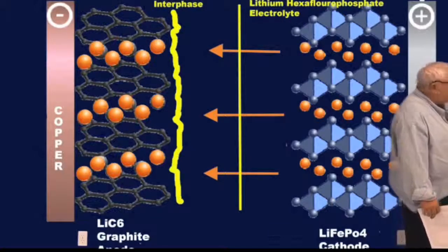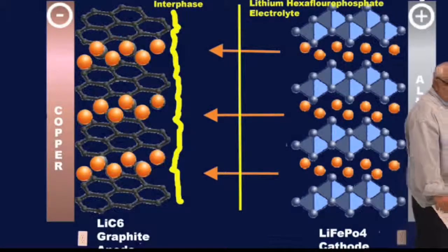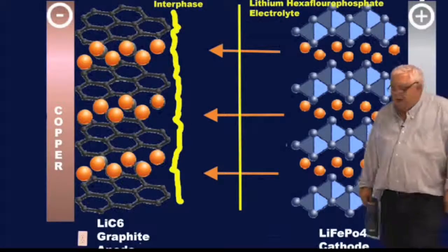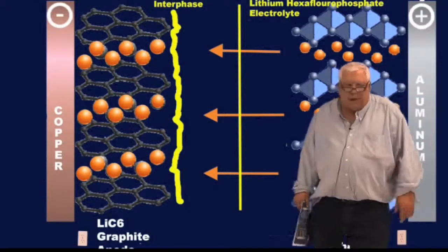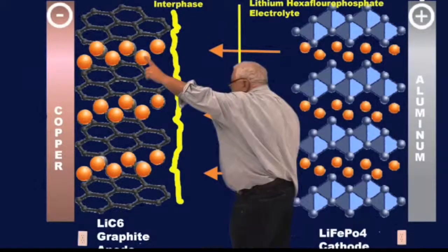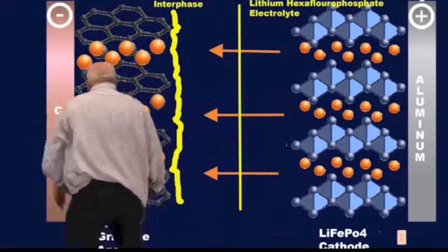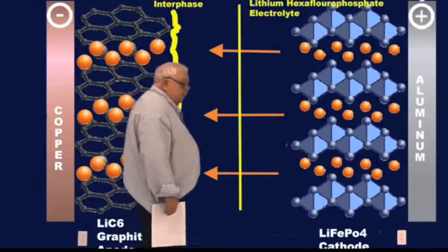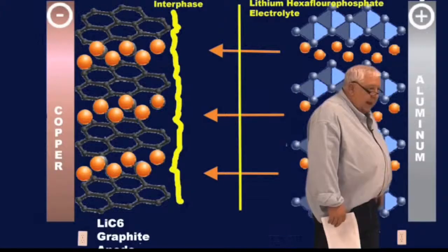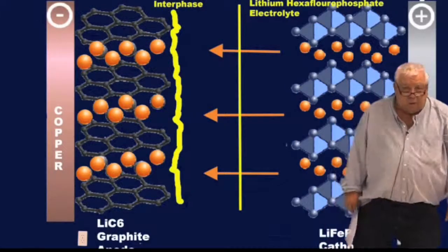But we have also removed electrons from the lithium that was in the lithium iron phosphate. And with every electron removed, that becomes more positive. When we send it around to the other side, this becomes more negative, and we wind up with a difference in potential of about 3.38 volts. And that's the way it is, and that's where it's at.